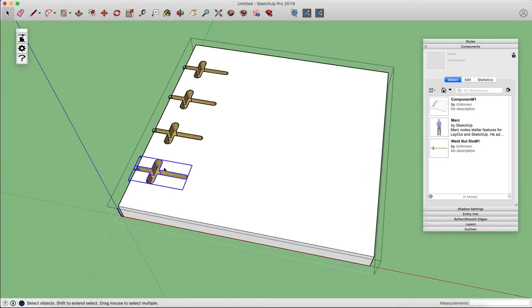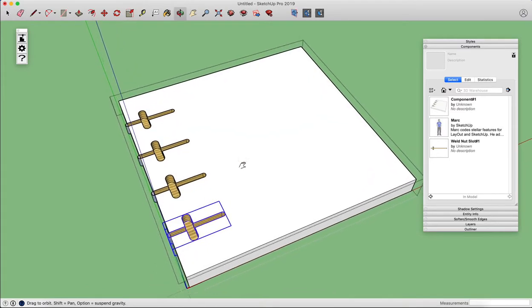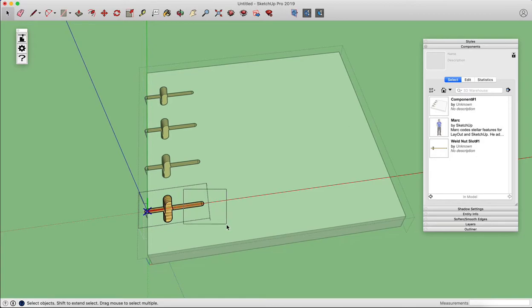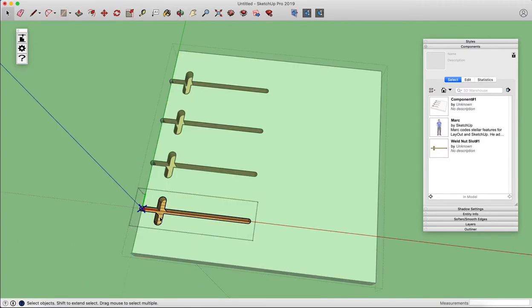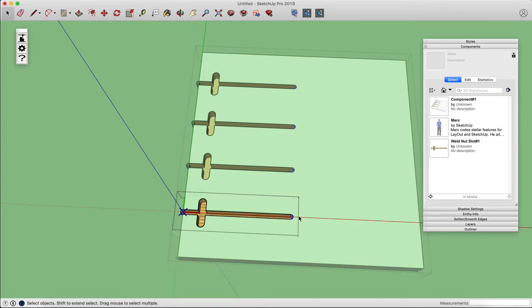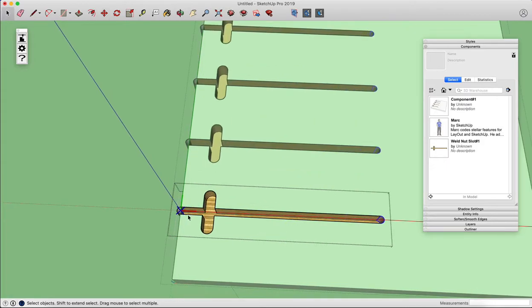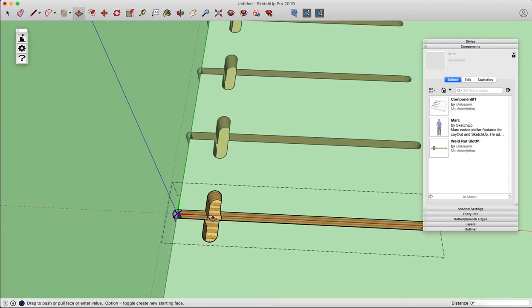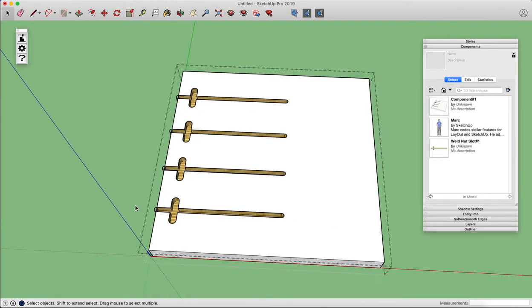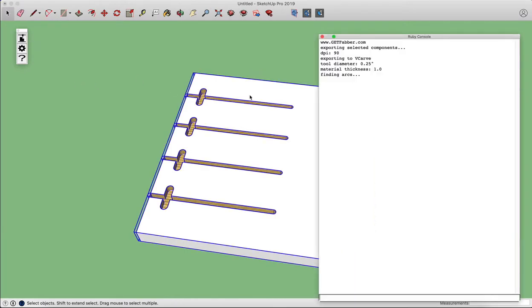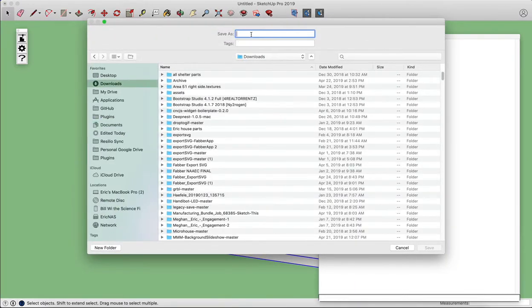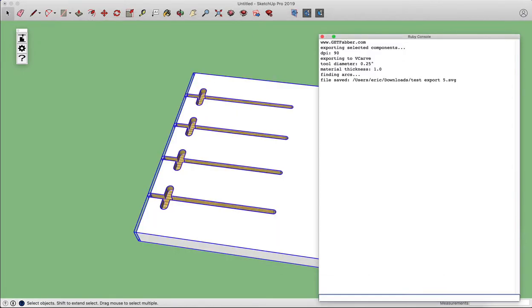So you now can make a slot or some other drill hole or any other detail as a component. So when you edit one, they all change. So I will go make these slots all wider, and you can see all I had to do is click into one and make an alteration to it, and whatever I do to one happens to the other. So say I wanted to make this all a little bit shallower, I could do that, and that change affects all of these subcomponents.